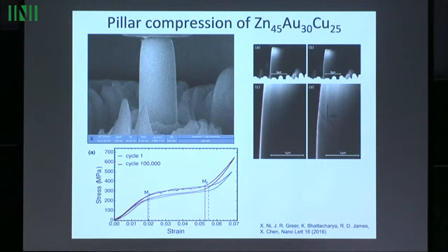It's called the effect of stress on transition temperature. It's the analog of the fact that when you take water to the top of a mountain and boil it, it boils at 90 degrees C instead of 100 degrees C. And in this material, pressure would have almost no effect on transition temperature, but uniaxial stress has a huge effect. So this was done by taking a bar of this material and stressing it until it transformed, and then letting go. And then you would get curves like this.